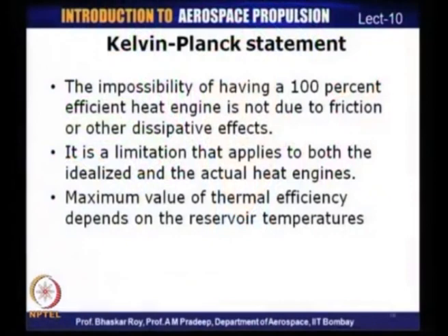So, Kelvin-Planck's statement puts a limitation on the amount of efficiency that a system can have, and therefore, this impossibility of having a 100% efficient heat engine is not because of frictional or other dissipative effects or real life effects, but it is a limitation which is applicable for both idealized as well as actual engines.